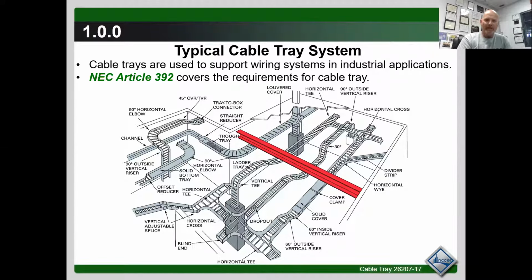The whole purpose of having cable trays is to allow a versatility. So if you're moving equipment quite frequently, it would make sense not to run hardwired into conduit and so forth. If you move your equipment around, it's easy enough to just move the wiring around. So lay it in and take it out of cable trays.